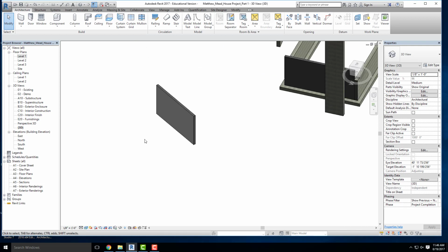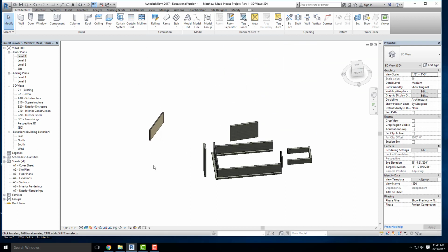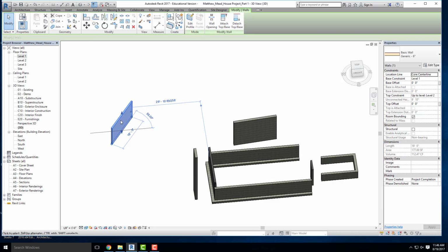Okay? So you can see how this becomes kind of tedious, but it's important that once you create them, you're only going to create it one time. So that's the nice thing about using the same file throughout the entire residence, is that once you create these wall types once, you're going to have them for the rest of the project. As you define them and put attention to detail in defining the wall types correctly, you're not going to have to go into your project later and start adding all that stuff. So when you create a rendering of the inside of your building, it actually looks correct. If you skip those steps and you're like, okay, I can't see the interior of my building, so what do I care what the material is? Well, you might not.